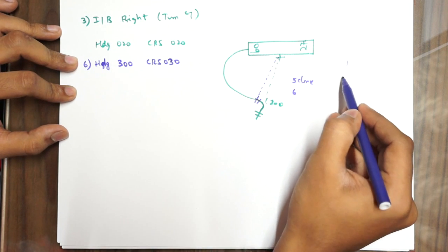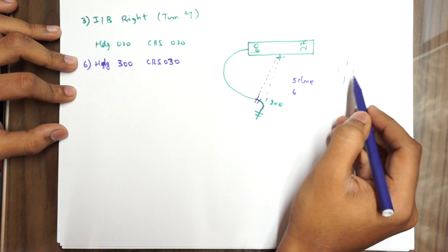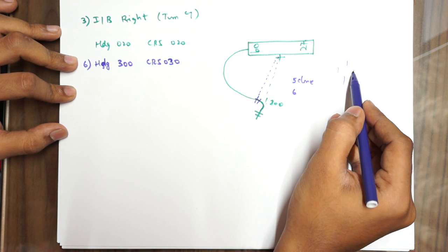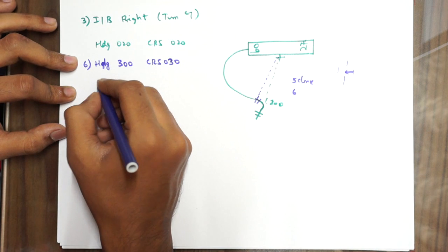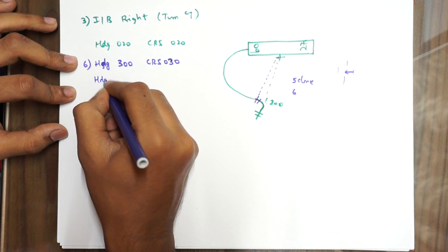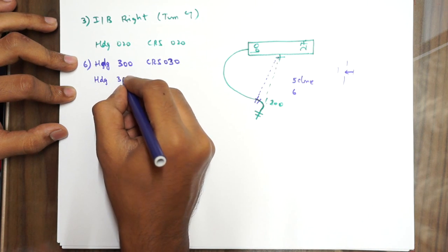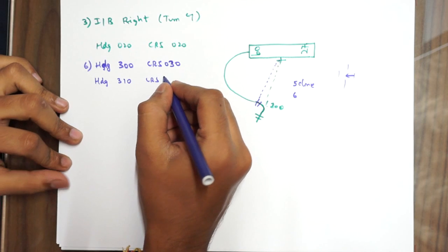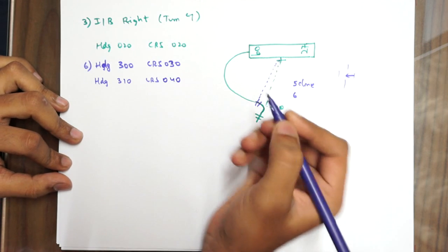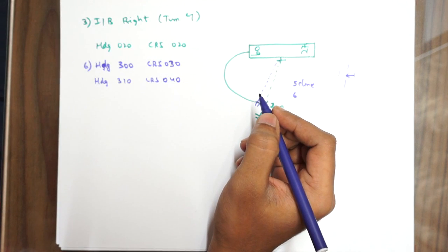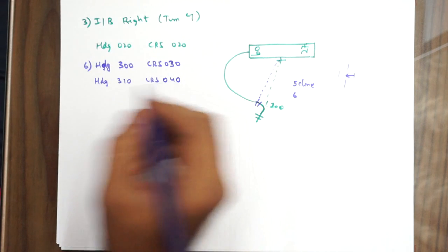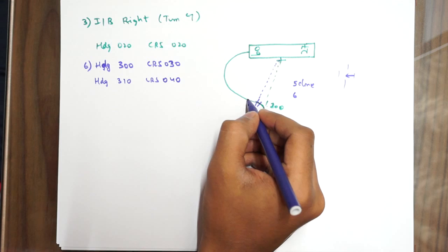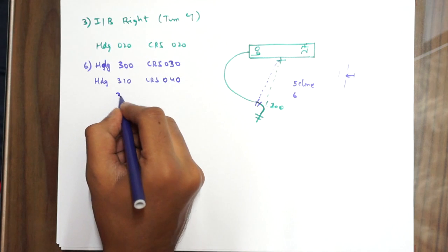So your needle will be either here or either, whichever depends on the side of the arc, and once it is on the center you will be approximately on 5 DME, and then you will change to 310. Course will be set to 040. Okay, so in this you will keep adding accordingly. Okay, and once you are again on the 5 DME, when the needle is in the center, you will go to 320,